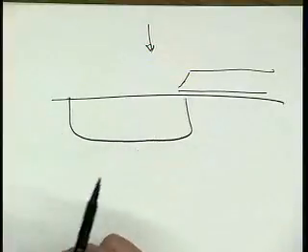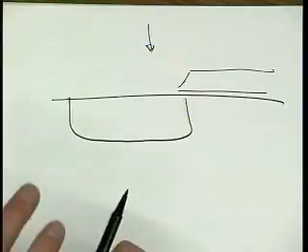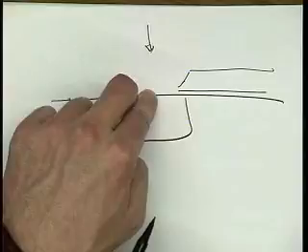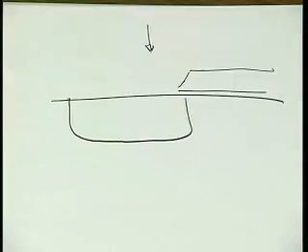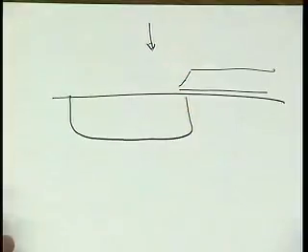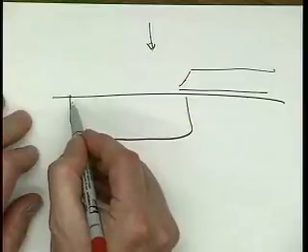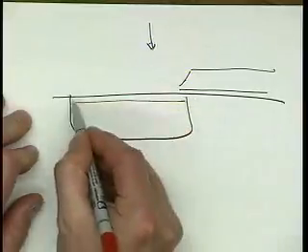And you know, I mean, if you use the thick metal, white bus, and so on, then you get into the source or into the drain region of your transistor, and you actually add more resistance there than in your entire metal interconnect. Well, the digital folks, they don't like this because it prevents them from making Pentiums that go at 3 gigahertz. So what they do is, or the processing guy does it for them, again, that's standard, actually, you don't even have to pay extra. Puts a silicide into this thing.